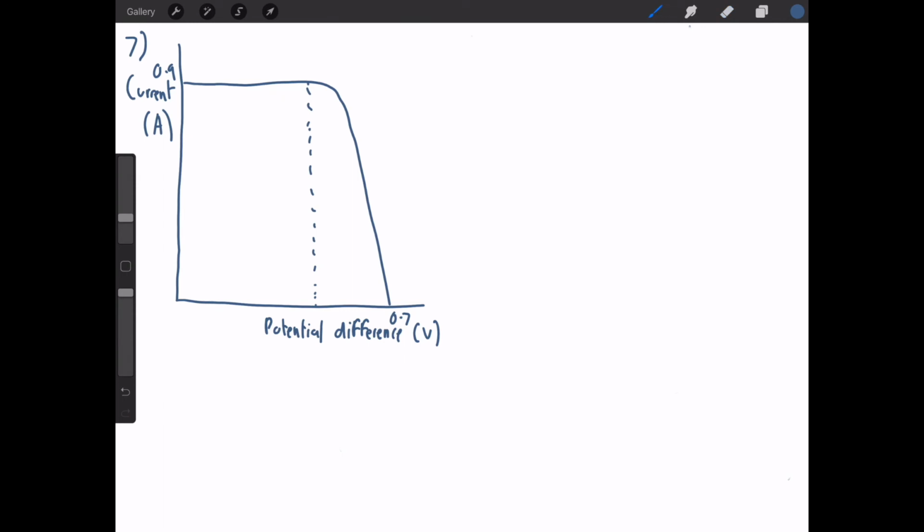A householder has 4 solar cells. Each of the solar cells has a resistance of 0.78 ohms. Explain how the solar cells should be connected so the total resistance is as low as possible. Well, with any circuit, if I wire things in series, so 2 resistances like this, then the total resistance, R total, is simply R1 plus R2. Now that's not what we want, because I'm going to have 4 resistors effectively in this circuit, and I want to get them to be a minimum resistance.